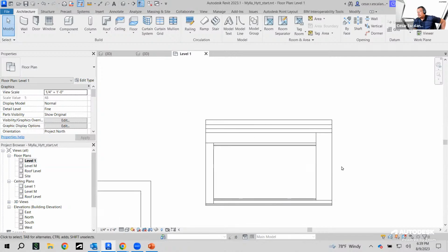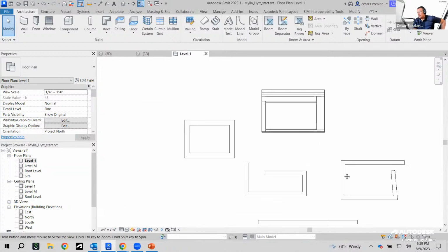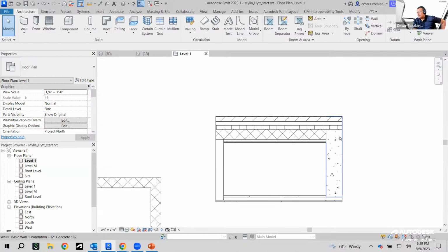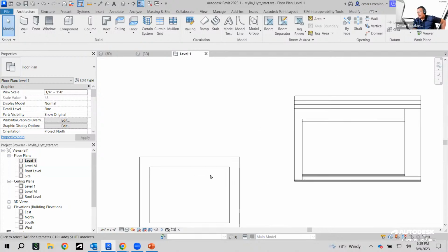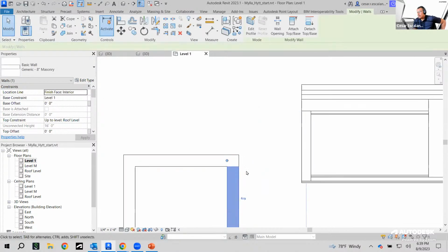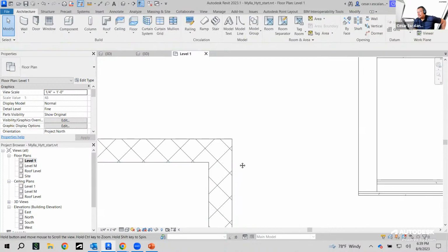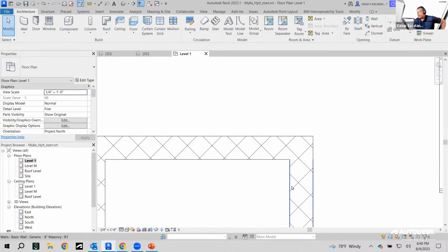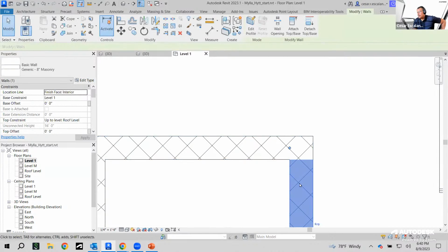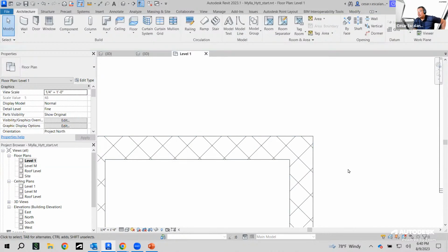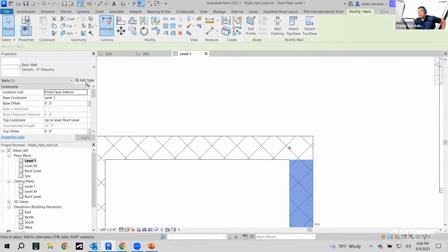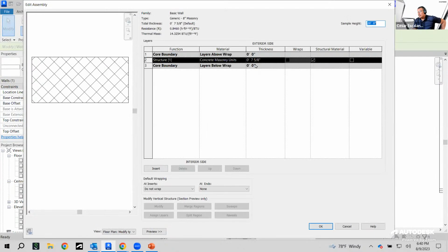All right. So another thing I wanted to show you is corner conditions. When two walls of the same type connect in a corner and they share the same materials, they merge and they look like a single entity. You see how this CMU wall wraps around and it's very clean, but this is because each of the walls has exactly the same material.